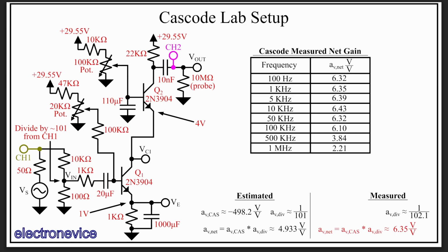This is due to a useful aspect of the Cascode I didn't actually discuss in this series of videos, that the Cascode can effectively increase the collector resistance to much higher than r_o. So the common emitter's effective collector resistance was 22K in parallel with r_o. The effective collector resistance for the Cascode is 22K in parallel with a much higher resistance. So that can improve the gain slightly in our situation, and is a much more important effect for active loads.